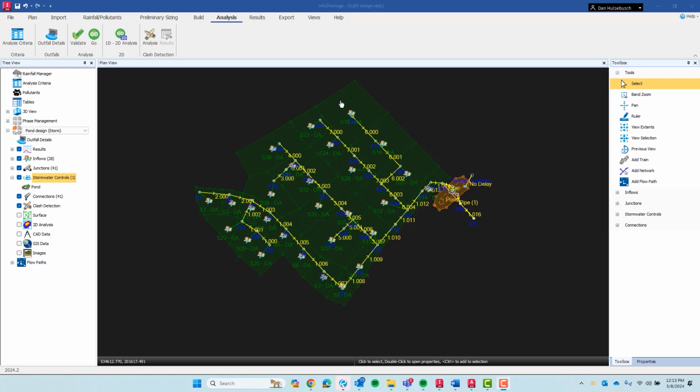So having gone over that quickly, what can actually be done in Autodesk Water? What you can essentially do is insert and create storm systems. You can also calculate runoff values by entering watersheds. If you create catchments within Civil 3D, all those catchments will come in here and load into Autodesk Water. That's what all these green boxes are.